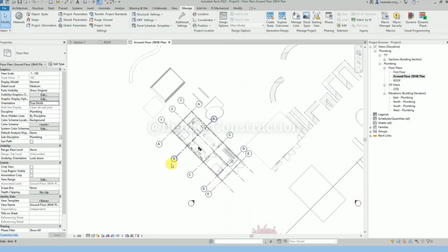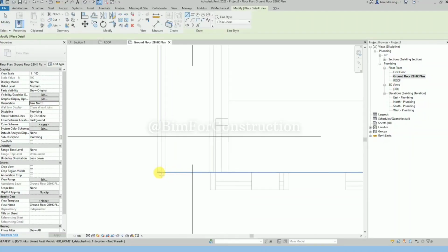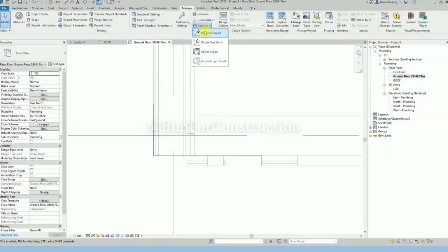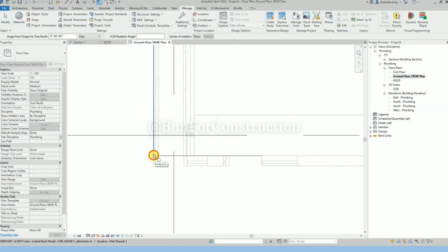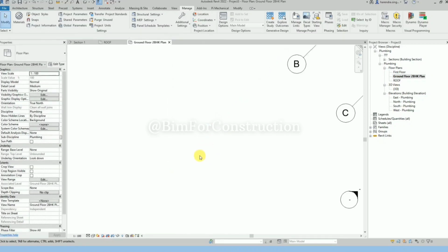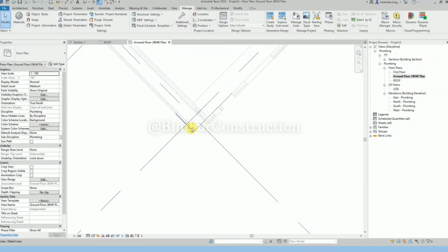Right now this building I have rotated 45 degrees, and this is how it is actually visible on site. But we can't work with this rotated building, because every time I have to draw a duct or pipe, it takes time to visualize things in the rotated building. And while cutting and putting sections, it also takes more visualization effort to work on this kind of rotated building. So I will rotate that building from 45 degrees to straight for my current project.